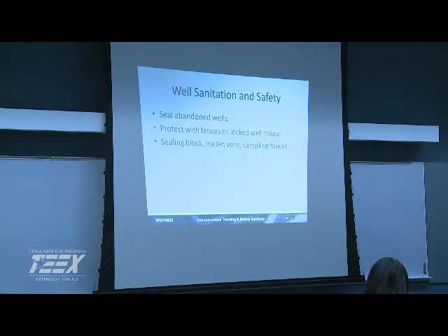Got to be a 6 foot cyclone fence with 3-strand barbed wire at 45. Got to be locked. Got to have signs. All of that stuff. Here, it just kind of depends on the facility. From my understanding, vandalism is an impetus to go in and put in fencing and all, but not everything needs to be fenced. Is that correct? So every state handles it a little bit differently. Any pumping station, primary, secondary, we ask that the wellheads be locked, that's something they can lock. So it just depends on the state, how they handle it.